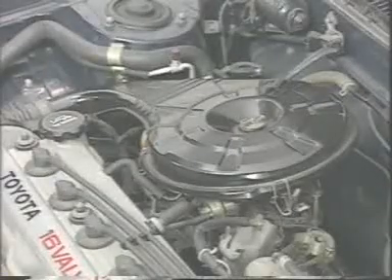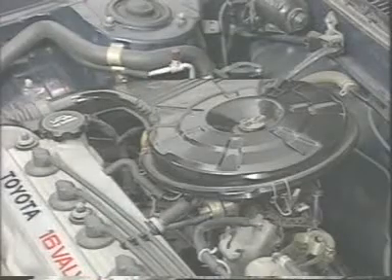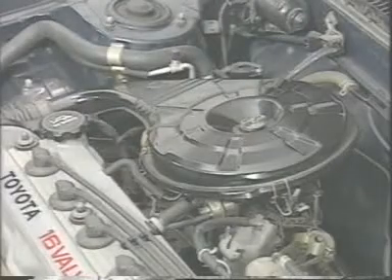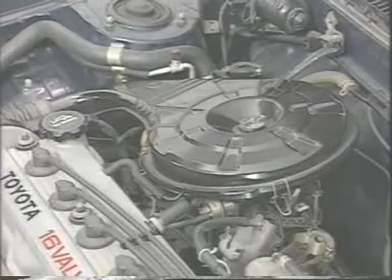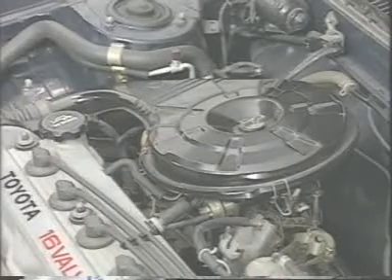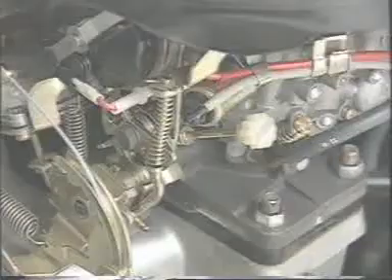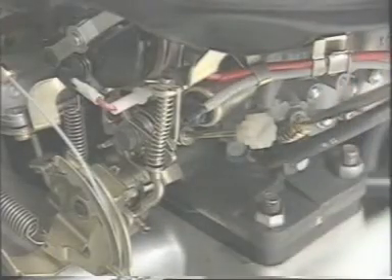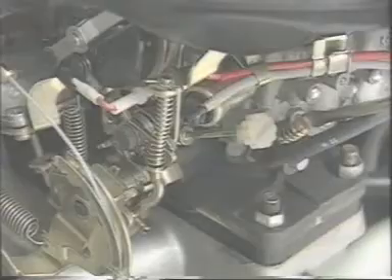Remember that the test must be done with the air cleaner in place. In some models with an air suction system, you must remove the air suction vacuum hose and plug it with a hose plug. Turn the idle mixture adjusting screw to raise the engine RPM to its highest permissible idle setting.